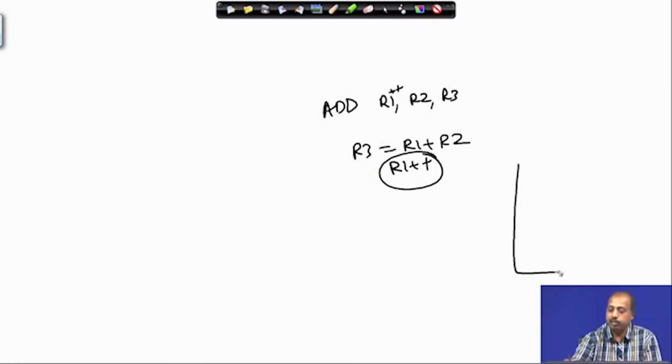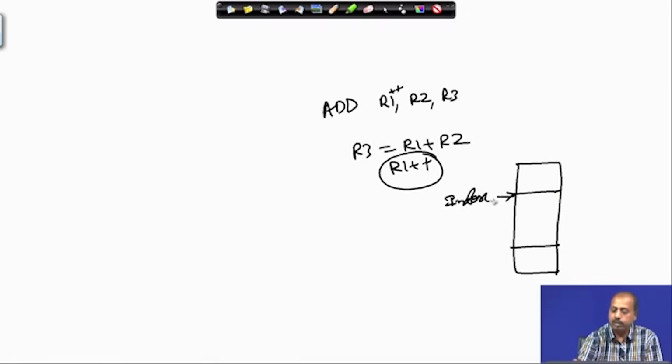Array is normally stored in a memory like this. There is the initial address, suppose the array is stored in this region of memory. So, initially you set your index here, the first location, then after this one has been accessed, you want that the index should automatically increase. If that is automatically done, then we do not have to spend another instruction for incrementing this index.